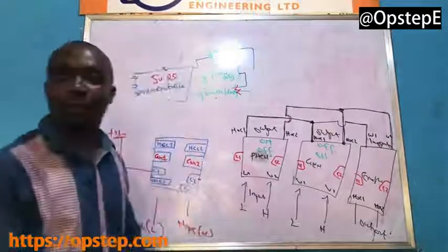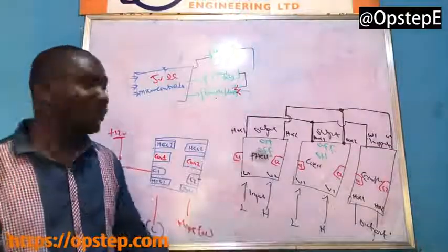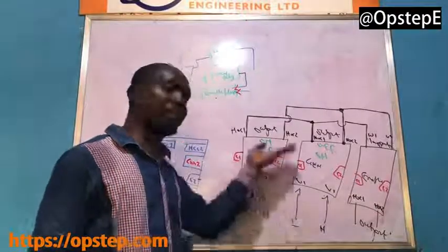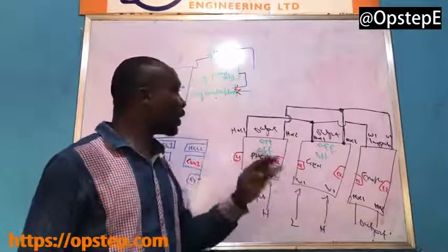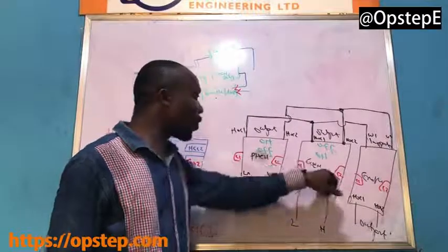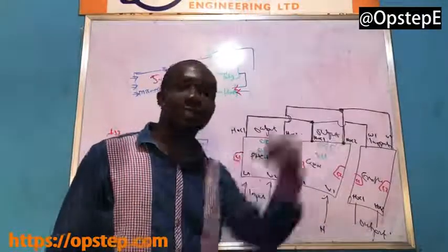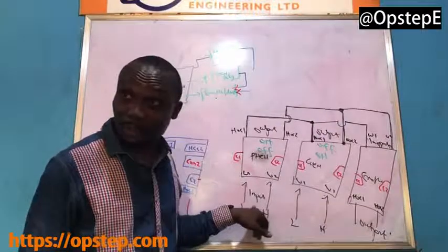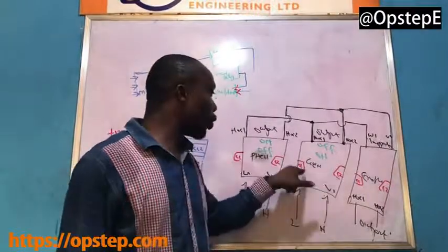It's simple. What you simply do is, first of all, on your generator. So your generator is on. So generator source is available just the way NEPA source is available here. But don't forget, the moment you switch to manual, it offs all the contacts of the relays, the coils of the relays. It offs this, it offs this, it offs this automatically itself. It now begins to get instruction from you. On generator, generator is started. So generator is available. Don't forget, NEPA is also available, just low. Are you with me? You now say, okay, on generator coil. So you on this coil and off this coil.